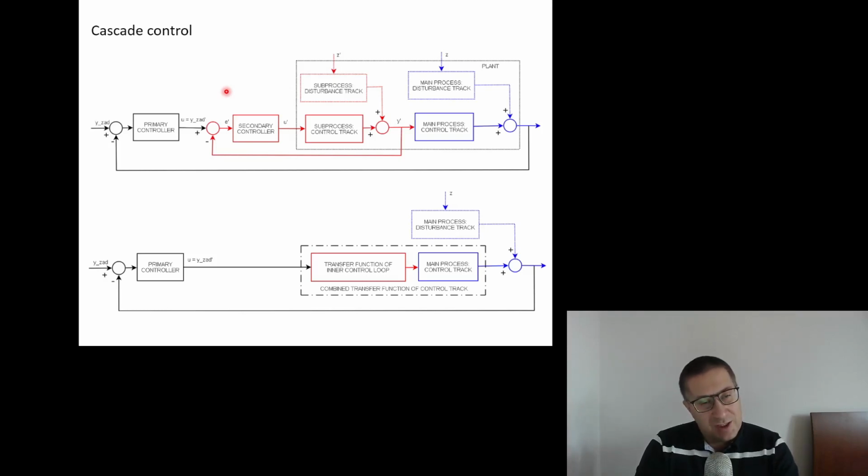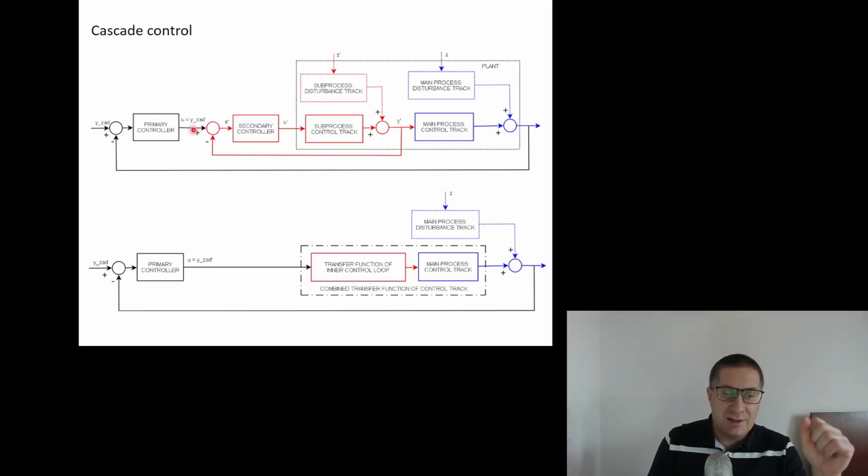And the question is, if we would like to have automatic control over the plant or part of the plant with the utilization of our AI algorithm, we need to decide where to place our hook, where to send the decision. Should we calculate the set point for the primary controller or the secondary controller? Every time we have to think about this.